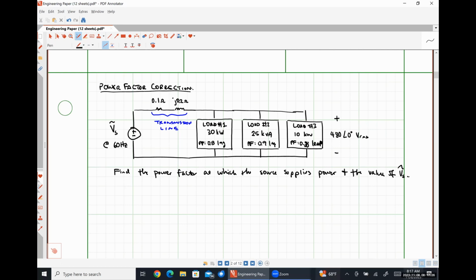So going way back to the second day of class, we talked about a little something called Tellegen's theorem. Tellegen's theorem effectively stated that the power supplied in a circuit has to equal the power absorbed in a circuit. So realistically, we could say that the power supplied by this source, which based on our current level of information would be difficult to get in one step, is going to be equal to the total amount of power absorbed in our circuit.